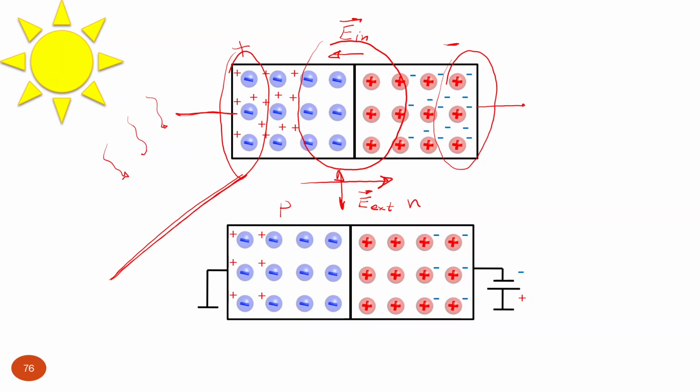So everything is stationary. Under this condition, we will have large diffusion current, and it will be compensated by large drift current, because the large diffusion current comes from the significantly increased concentration of minority charge carriers, and the large drift current comes because of forward bias, which we build up under illumination and the open circuit condition.